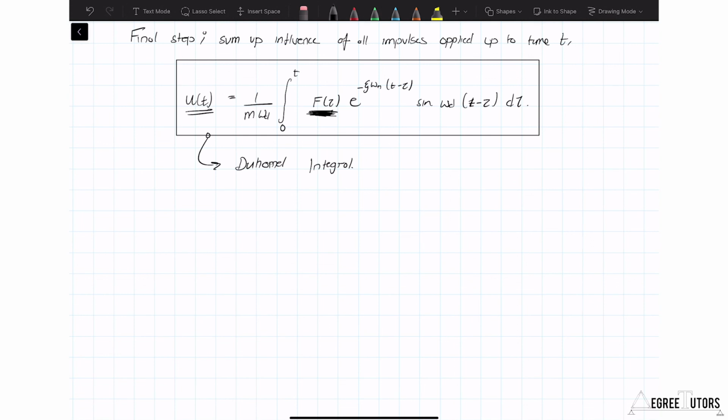due to coupling between the dynamic system, the bridge in this case, and the people that are generating the force on the bridge. And the most famous case of this is obviously your London Millennium Bridge, where you had a feedback between the crowd walking across the bridge and the oscillation of the bridge. The oscillation of the bridge altered the behavior of the crowd in such a way that their ground reaction forces were increased, leading to a larger force on the structure, exciting the structure more, and there was feedback thereby set up between the crowd and the bridge.